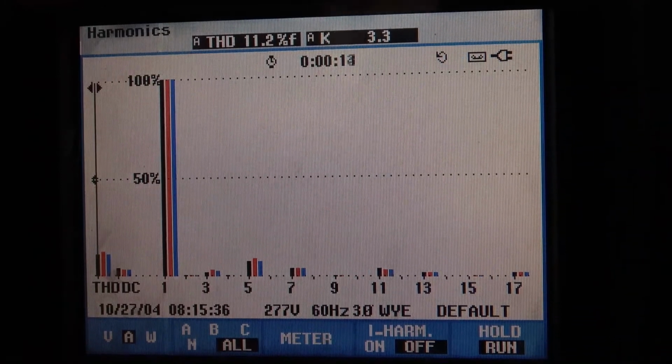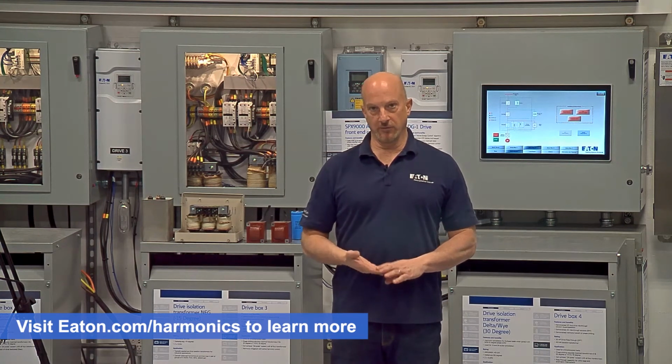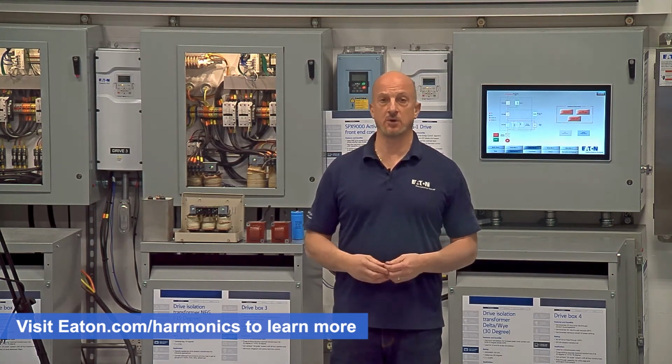So ultimately what we ended up with was taking a 6-pulse drive, putting a drive dedicated filter or a broadband filter in front of it, and it turns it into what would be essentially a 12 or 18 pulse drive.